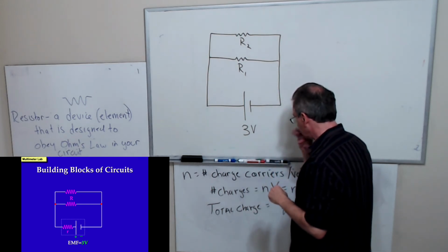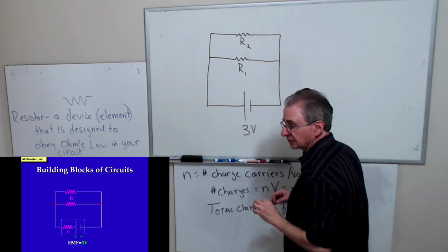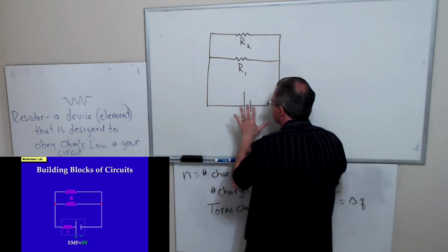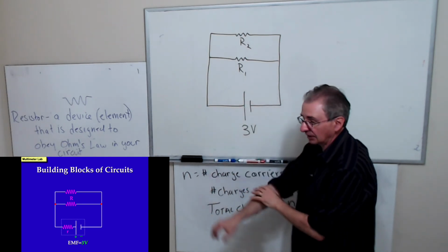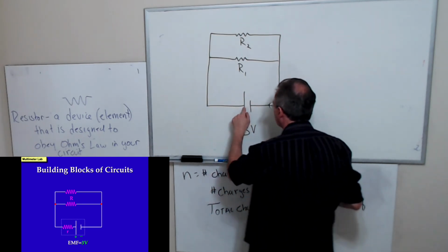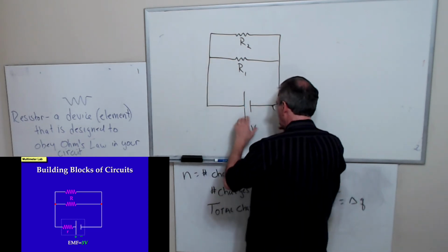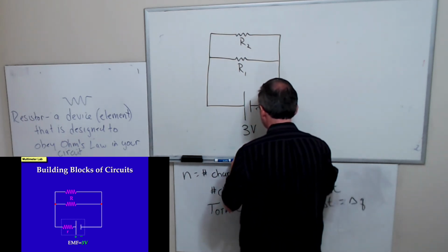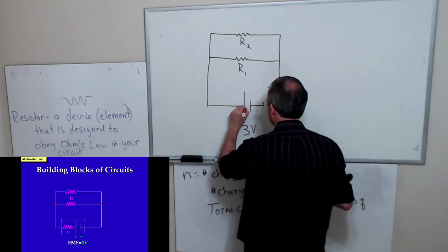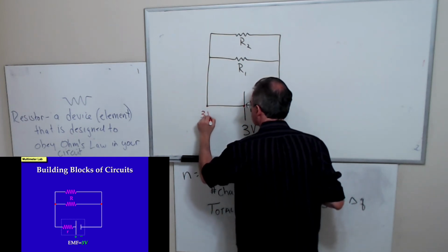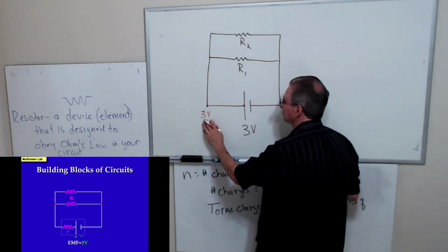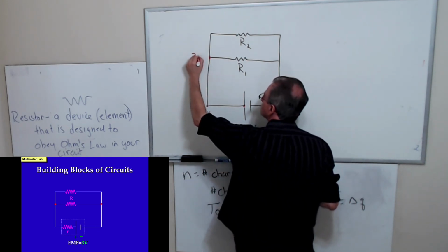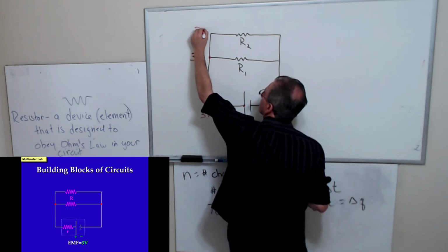Idealized version. So when I make this electrical connection, like this is a wire. This is basically a map that tells you how to wire the circuit. So I'm going to take a wire and go from here to here. Now the wire, again, we're assuming really has no effect on my circuit. So if this point's at 3 volts, this point is also at 3 volts. If this was not ideal, this would be a different value. This point, on the same wire, is also at 3 volts.